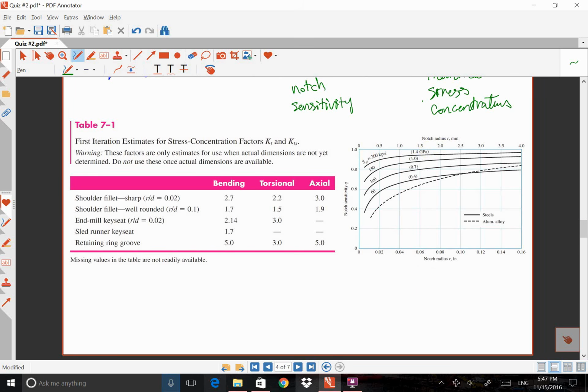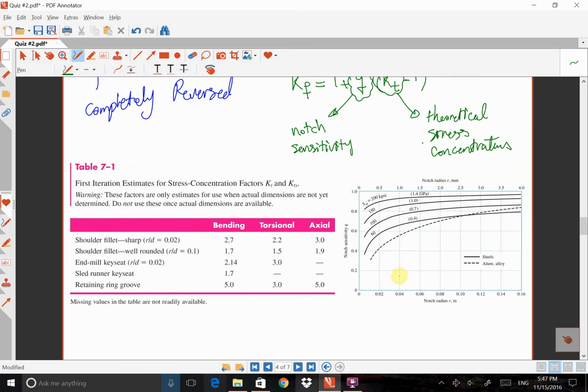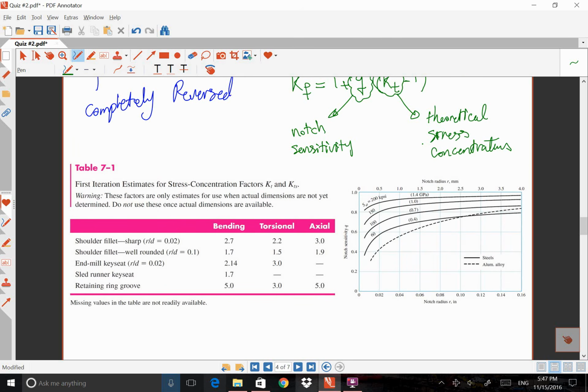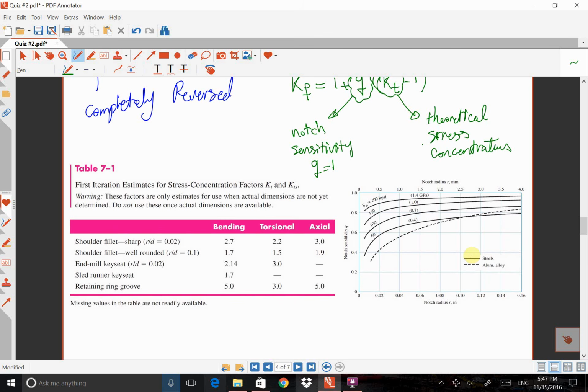So if we consider q to be 1, it's not an unrealistic assumption. That looks fine to us. Okay, so this q is 1 in this question, and this Kt should be found from a table in Appendix 15 or 16.